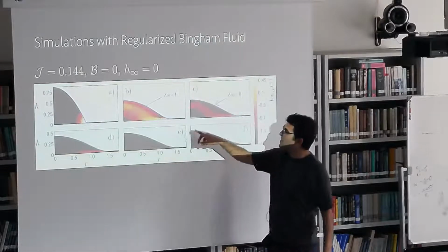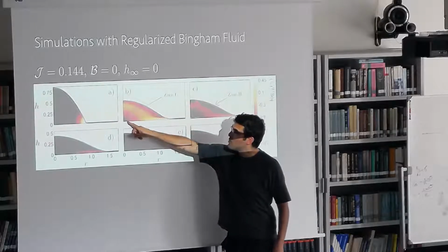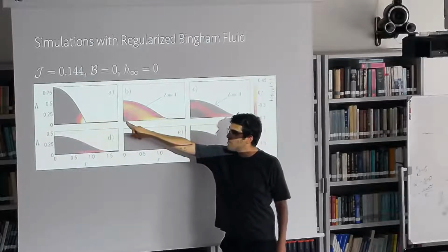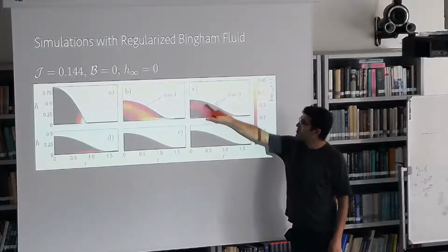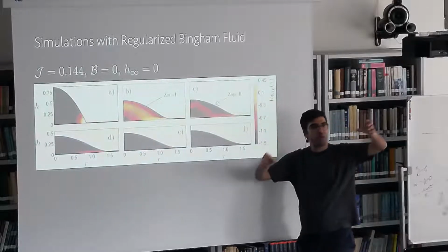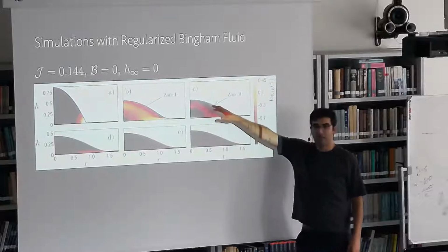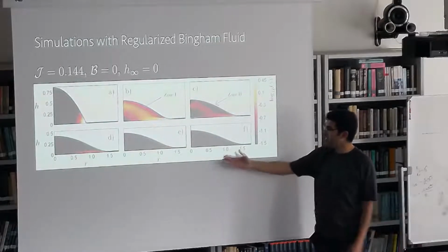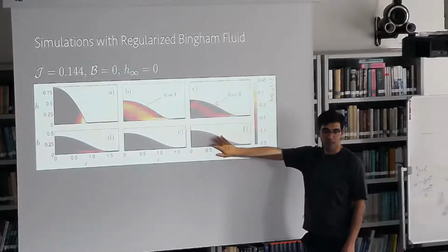There are a couple of interesting things about the anatomy of the flow. One, at the center, you get this zone that looks like a static plug, so nothing moves, fluid doesn't move there. That's also a stagnation point. And you also get these zones at the interface where there's a moving plug. So you also get low deformation as it moves with the interface, basically. And the important thing is that if you wait long enough, you get a shape where everything is black, meaning that nothing moves here. That's your final shape.